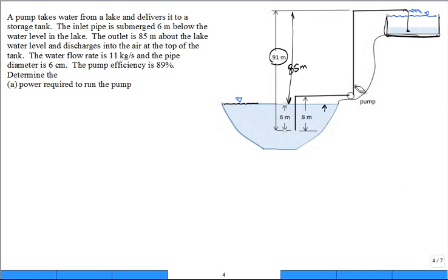Another reason is maybe there's a break. Somebody has a valve right here, they don't think about it. Either there's a break in the line or a valve somebody opens and all of a sudden it starts gushing out. True? So often you don't submerge the outlet into a tank, because what you dump into the tank, you don't want it to, unfortunately, inadvertently be sucked back into the system.